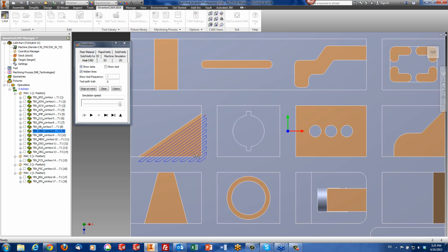These lines, since they have less of an area to clear, are shorter, since it wasn't a clear offset but rather a canned option. The clear offset would have actually given you a line that would have been starting from here, going up until here. Using this option, it automatically trims it and works only where it needs to work over here.